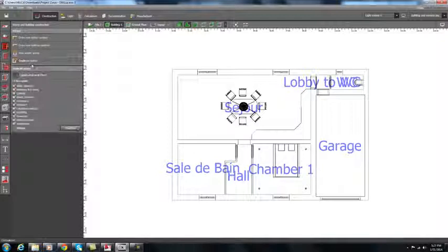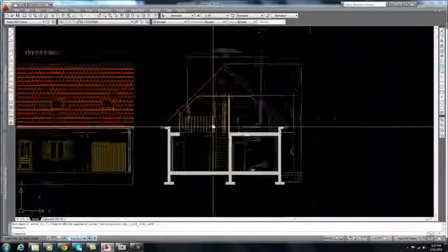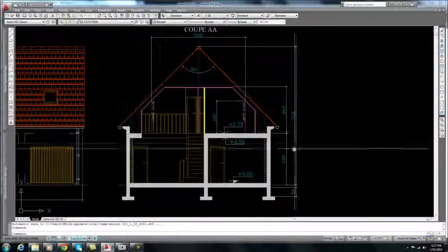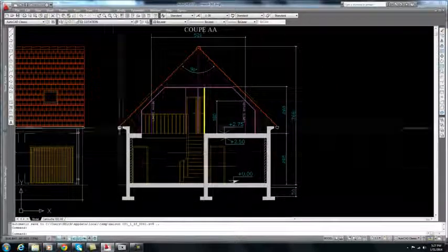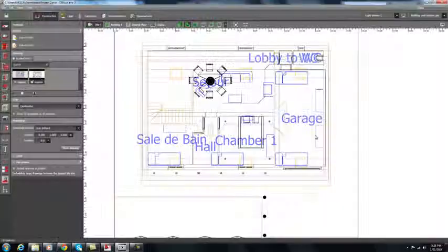Here I want to show you the options. In our case, we don't need to copy the ground floor because this is different. Our ground floor is so different from the second floor. If it's typical, like for a multi-story building, sometimes the 3rd floor is typical up to the 10th floor, then you will copy it as a typical one, or you just duplicate it simultaneously. But this one is totally different, so we don't copy it.